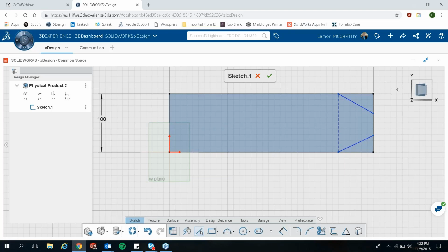And now we're going to make a center line down the middle of the entire solar panel. As you see, this triangle appears instead of the circle. This automatically relates to the midpoint. And again to the other side. We're going to be using this simply as a construction line, so if you go ahead and select this here, on the pop-out ribbon we do have a for construction option.